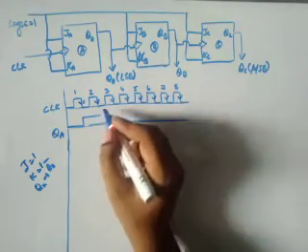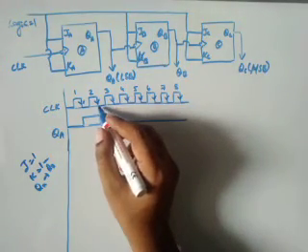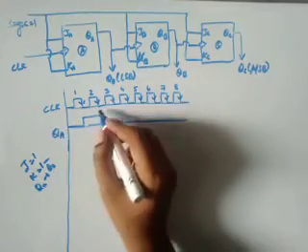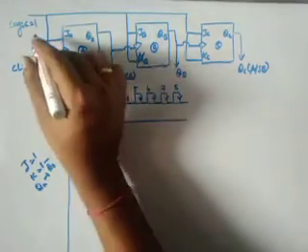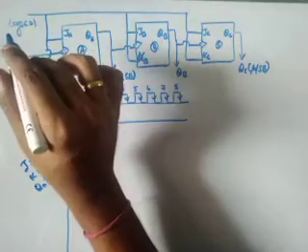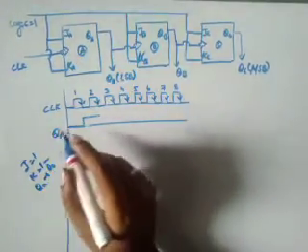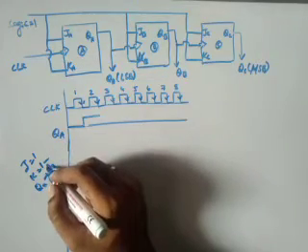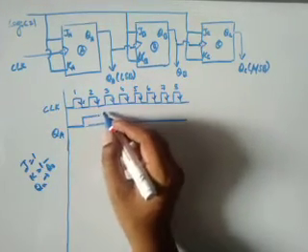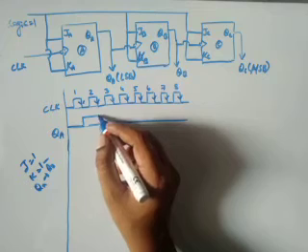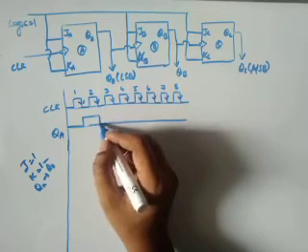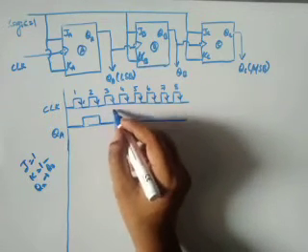Again, once it senses a negative edge, it looks at the inputs. The inputs have not changed; they are always 1, J equal to 1 and K equal to 1, so whatever value is there is complemented for the next state. So next it is going to have 0 up to the next negative edge point.